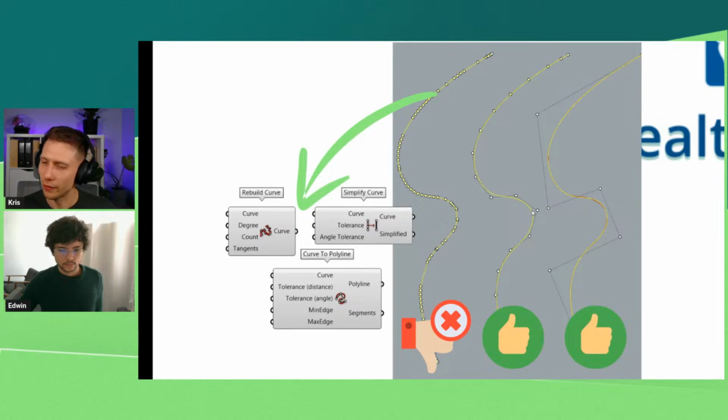And as I said, if you don't care that much about tolerances, you can easily change this to a polyline, and you will see the difference when you are going to make some loft sweeps. If you are doing that on a polyline, it will be maybe five times faster, because the mathematical expression is really easy to follow.